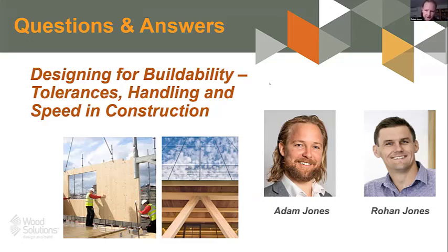Your compliance pathway, let's say a lot of the time the amount of fire testing we've built up over time means we don't necessarily need fire testing as much, but if you don't have as many different connection types, it's more likely that fire testing will be minimised or completely eliminated. So putting all the focus in connections, that's where most of the design energy goes. Probably 80% of the design is in connections, not just the design of elements. That's pretty straightforward stuff. So looking at that, and in particular the replication as much as possible.